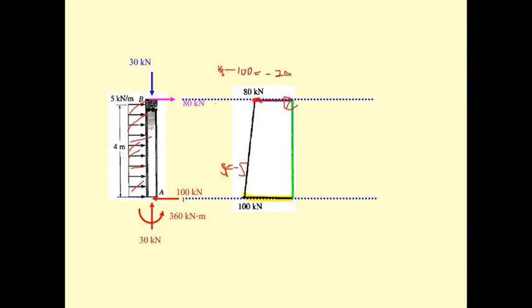And then if you move this one, the V sub B is going to be minus 20, plus 100, and then you get the 80. And when you get this 80, the pink force just closes the loop. Next we have the moment diagram like this. Why is this in this direction? Because clockwise is positive, counterclockwise is negative, so the moment here is negative.